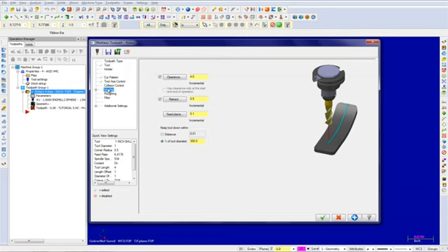Select linking. Change the clearance value to 6. Change the retract value to 5. Change the feed plane to 1.5. And keep tool down within should be set to percentage of the tool diameter, 300%. Then select the OK button to generate this toolpath.